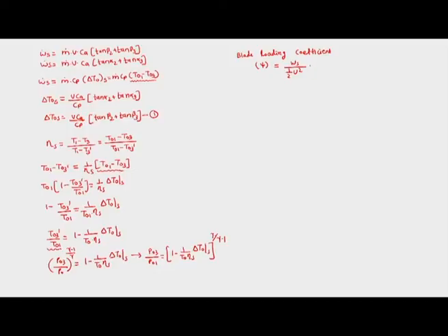This is the specific work, so we would have no m dot here; we would have it as Cp into delta T0 stage divided by half u square. Delta T0 stage we can put over here and calculate what is psi, or the blade loading coefficient, in case of a stage of the turbine.